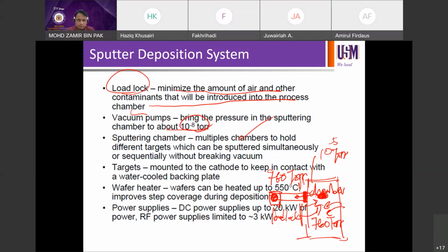A sputtering chamber depends on what you have. Some are industrial scale, some are lab scale, and some come in multiple configurations, with multiple chambers to hold different targets. So if you're talking about different target materials, then you may need to use different chambers. For example, like I told you about Fuji Electric, 20 different chambers. When one is done, the gate valve will open, transporting to the next chamber. Done. So that is multi-layer deposition.